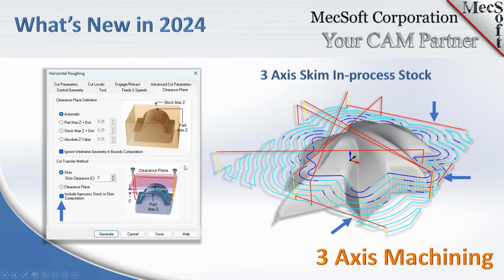If you have a rather complex part, as you can imagine, or may have run into, there's a lot of retracts up to the full clearance when it didn't need to be. Another note, actually: in previous releases, we were looking at only the part geometry, and we computed the Skim clearance from that. So what Don is saying is absolutely correct in that the Skim clearance moves will reduce your moves all the way up to the retract plane and thereby enable faster machining.